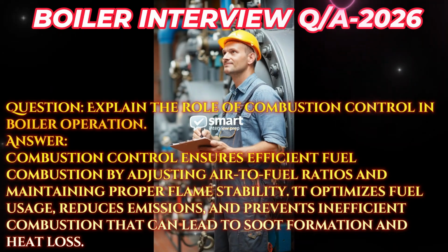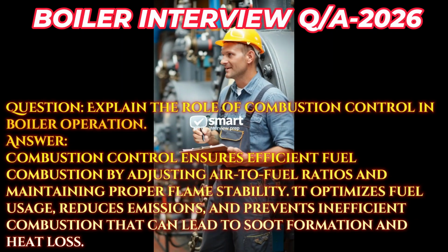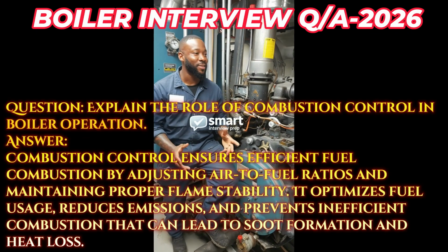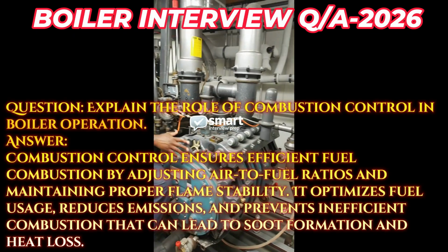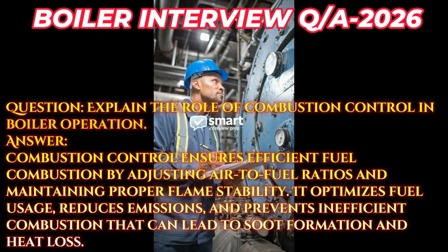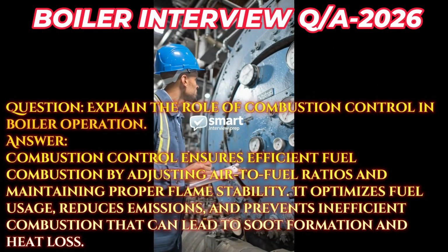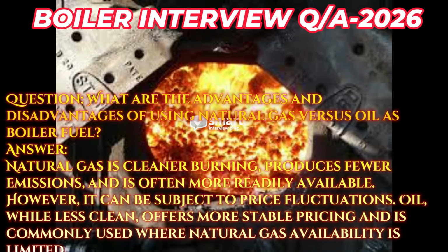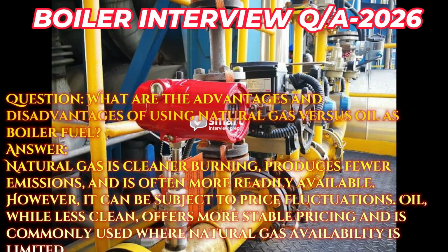Answer. Combustion control ensures efficient fuel combustion by adjusting air-to-fuel ratios and maintaining proper flame stability. It optimizes fuel usage, reduces emissions, and prevents inefficient combustion that can lead to soot formation and heat loss. Question. What are the advantages and disadvantages of using natural gas versus oil as boiler fuel?